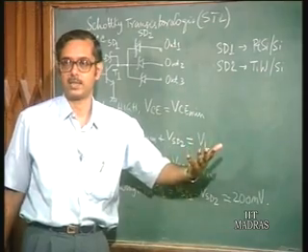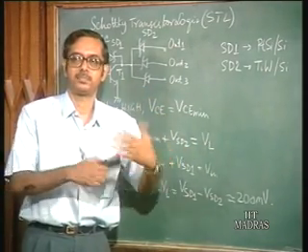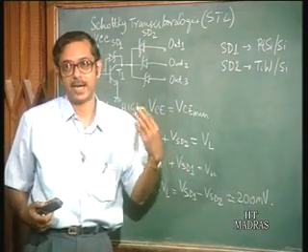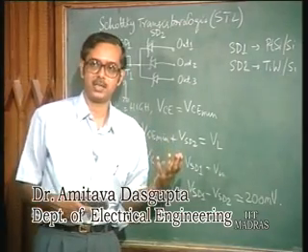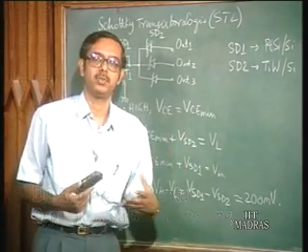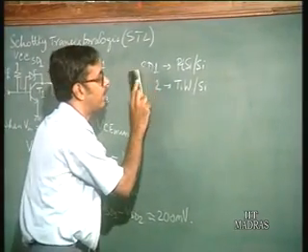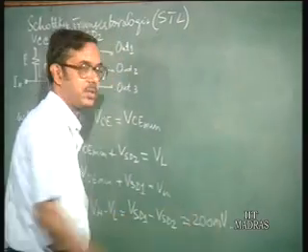Okay, so it is going to be faster. If it had to charge through a higher voltage, it would take more time. So, for any high speed circuits, one has to sacrifice noise margin, and the logic swing has to be reduced. So, that is also another point in favor, if you are looking at it from a high speed circuit point of view.